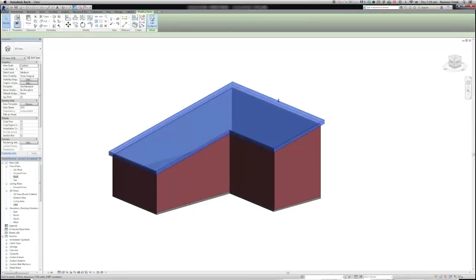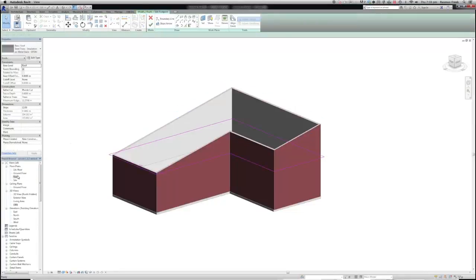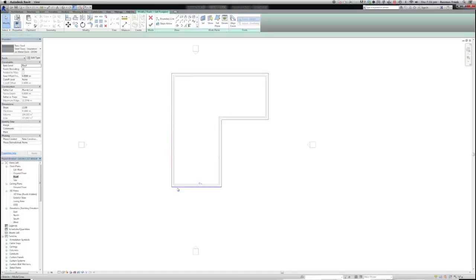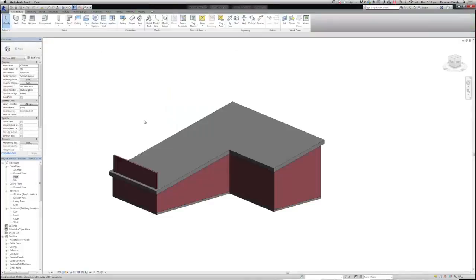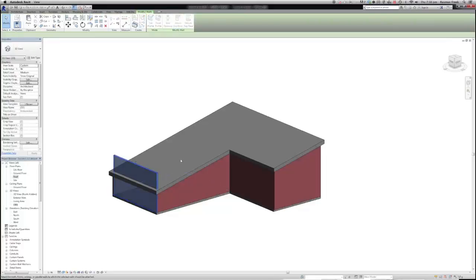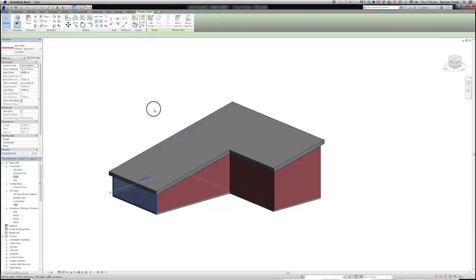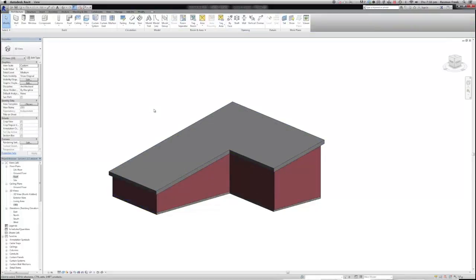Now, let's see what happens if we change the walls we have defined the slope for. To fix this wall, again, use the Attach Top tool. In the 3D view, we can see that whatever edge has been assigned a slope, it will project that slope in both directions. In this case, that leaves us with a small wall in the south side of the structure.